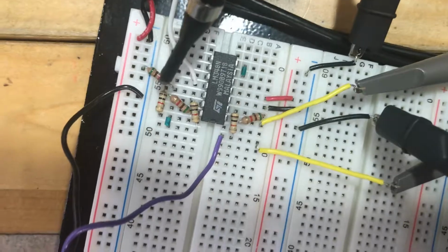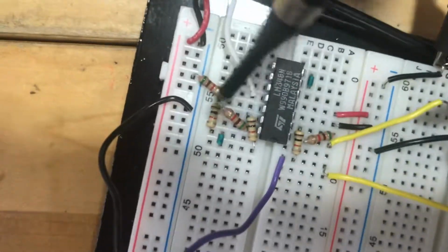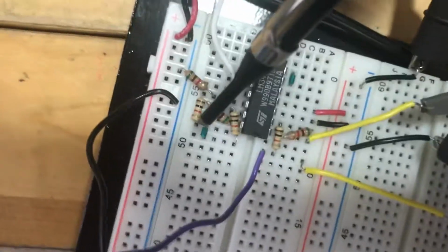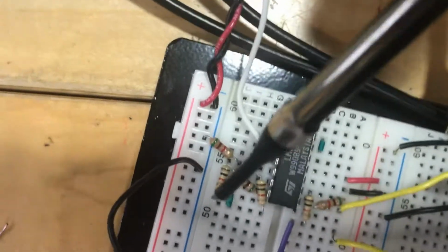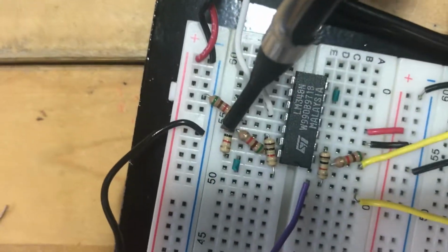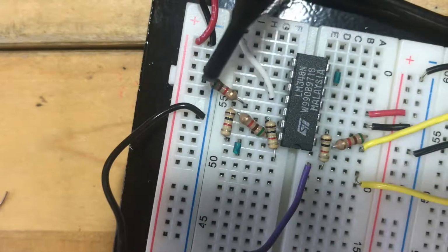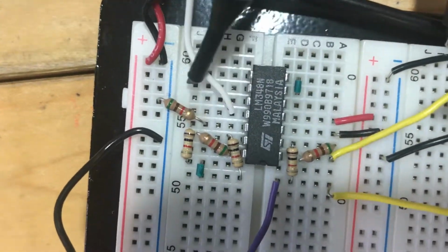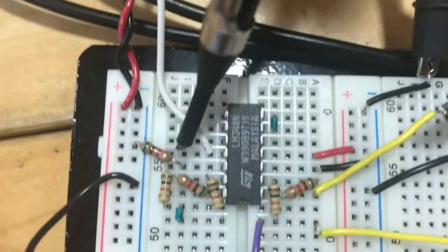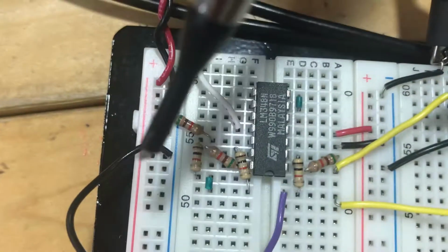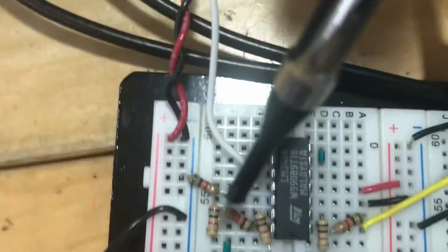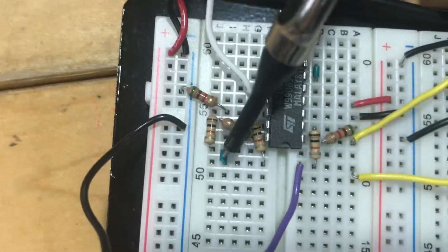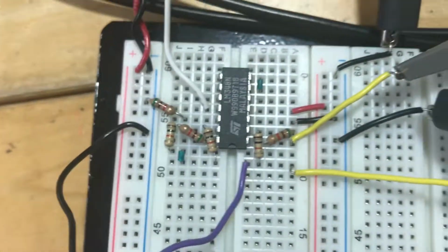And here is the differential op-amp. Right now it's in the common mode gain configuration, but we have R1 and R3 about 1 kilo ohm, and R2 and R4 about 5.1 kilo ohm, so the gain V2 minus V1 should be about 5 here too. But when we're in the common mode gain configuration, the gain's going to be much lower. It should be basically 0 because V1 is equal to V2.